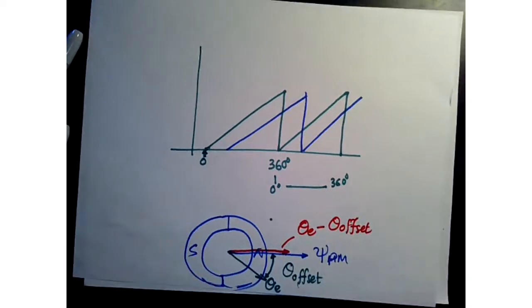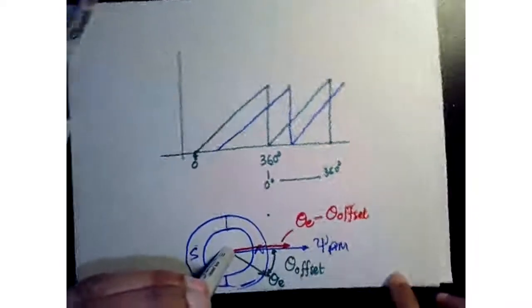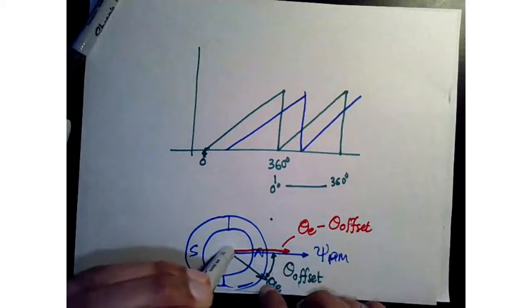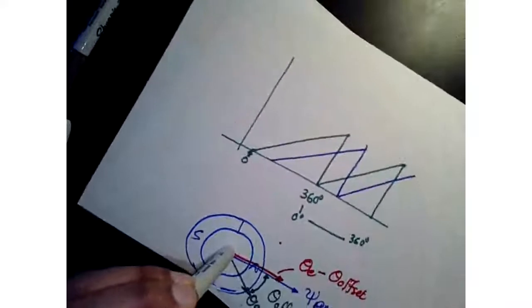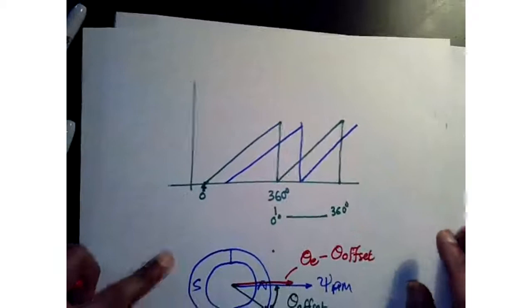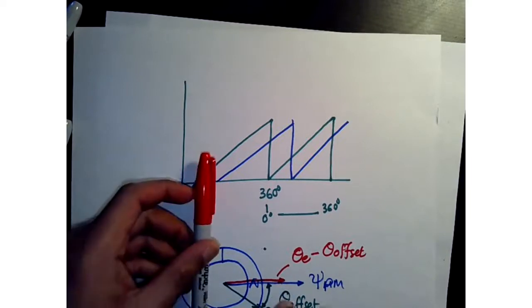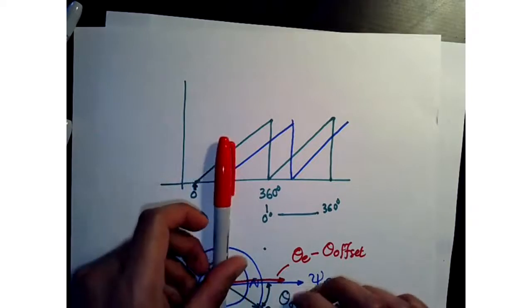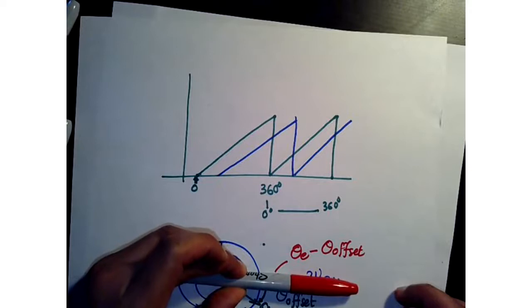All right. So when you do that, even though you are rotating, that correction is constant, and it's following the rotor flux. This is a very important concept, and if you don't have that proper alignment, you could end up with zero torque, because if the offset is too large, you might apply your stator flux right along your permanent magnet flux.